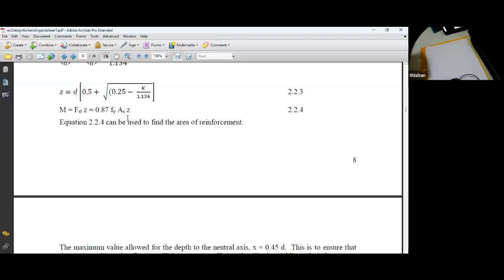And the value engineer will certainly provide all the knowledge needed, but he cannot provide the supervision. Supervision has to come by employing a lot of young engineers who can provide 24-hour surveillance. Even if a concrete pour is done over 24 hours, there will be 3 shifts of engineers who will take over in 8-hour shifts. You can't have one engineer doing, say, 18-hour shifts or something like that. You have to have many engineers doing 8-hour shifts, so that the quality controlling and quality assurance part can be properly